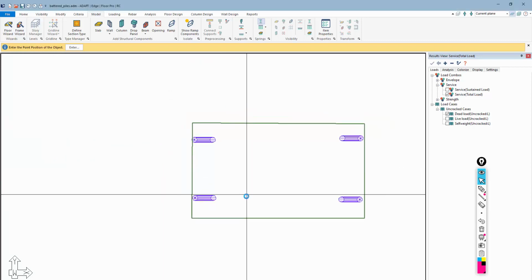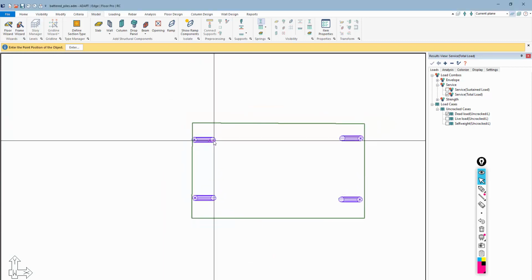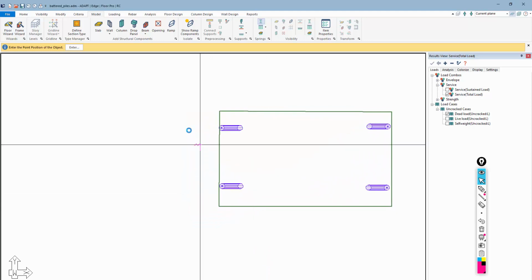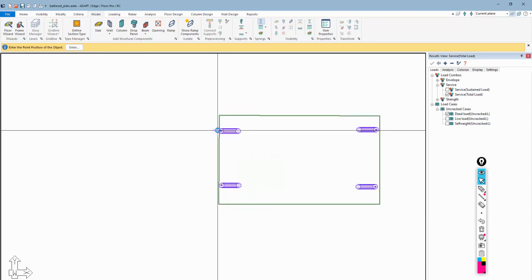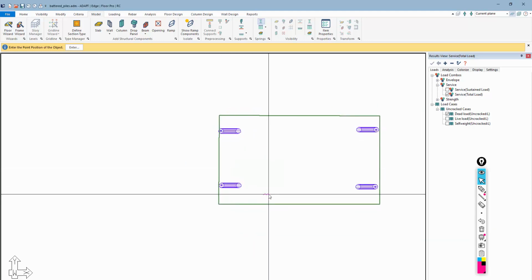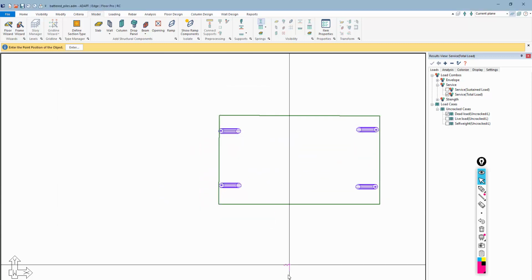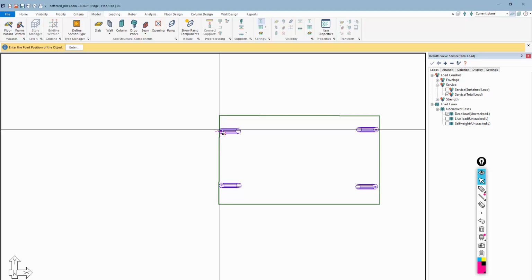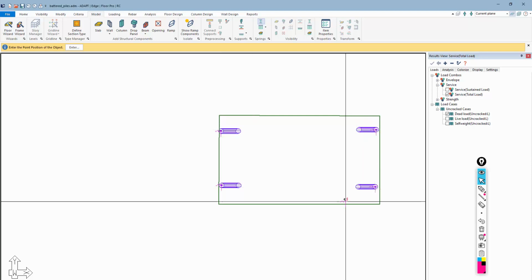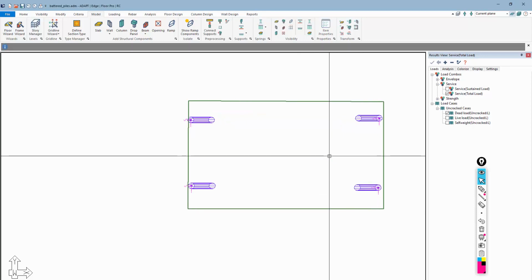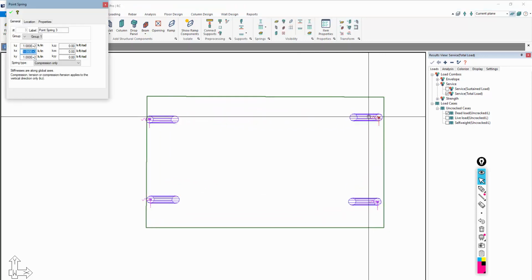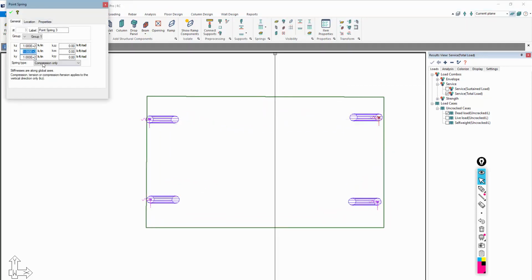So when I place this spring, I'm actually going to place it just here at this location where we have this point support. So it's 240 inches down, and then wherever I place it, there. So I'll turn on this option there. I'll just add the spring kind of where I have those point supports. We know that the point supports are essentially zeroed out, and now those springs are shown like so. So the location is down 240. This is the coordinates of the springs.